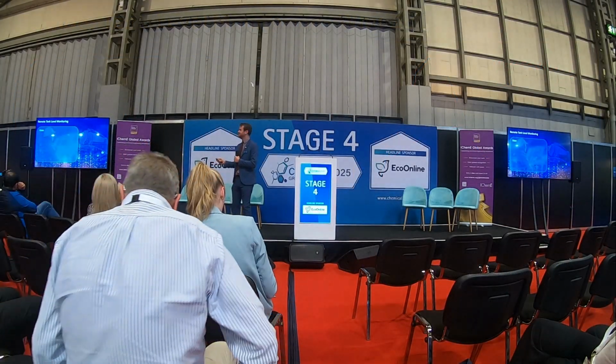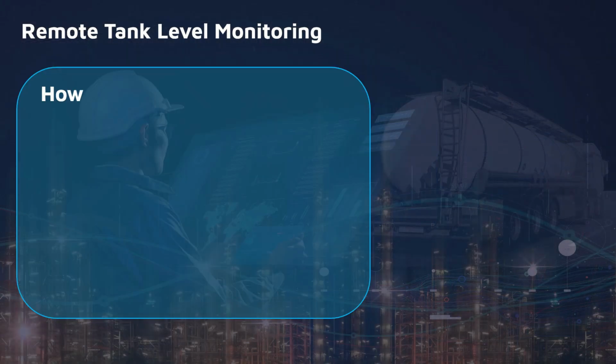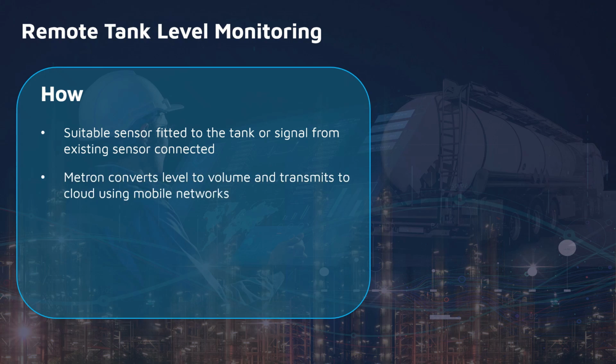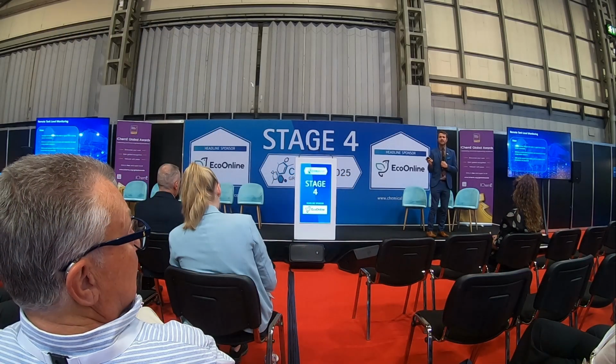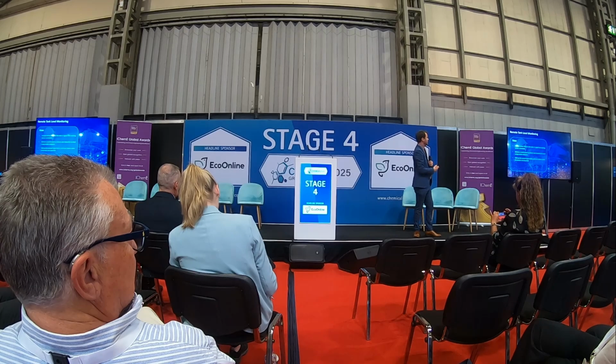Here's how we did it. We got a sensor and put it in a tank. Or we got existing sensors and connected them. We convert level to volume, and we do a bit of contextualization on that level. We transmit it to a platform where we can get that. We use the public mobile networks to extract that data so it can be used almost anywhere in the world.